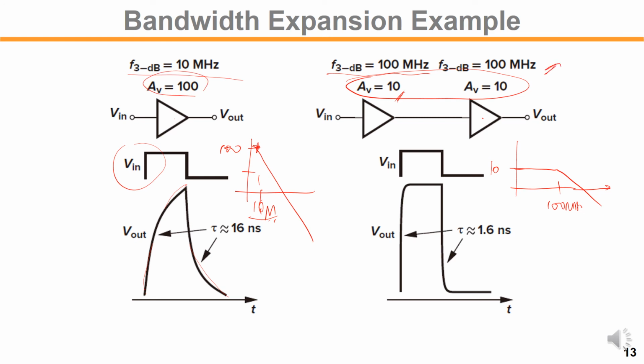But the bandwidth is close to 100 megahertz compared to 10 megahertz. So the output response will be pretty sharp, right? You will follow the input square waveform more faithfully.